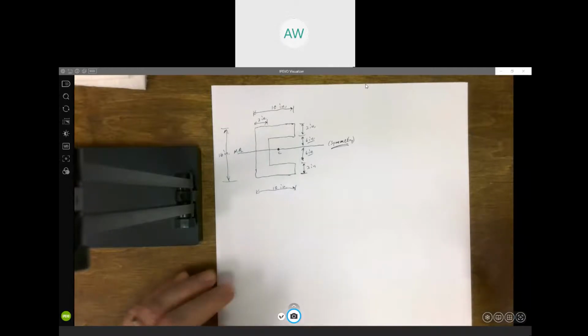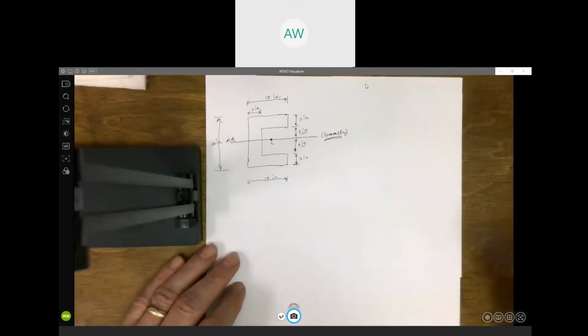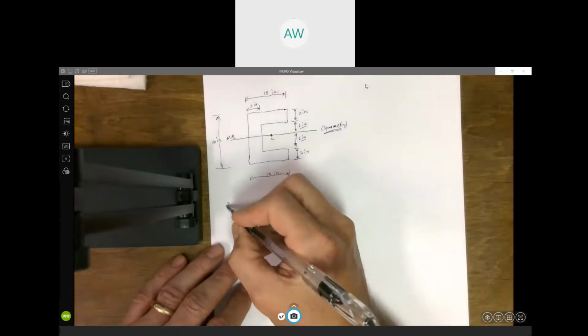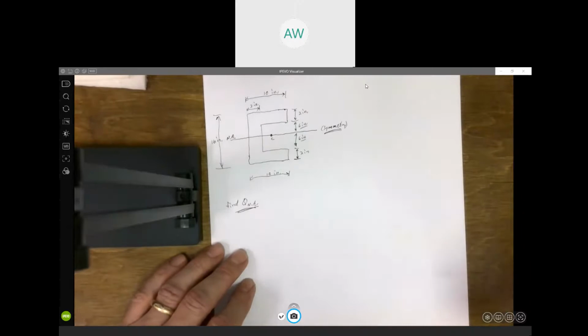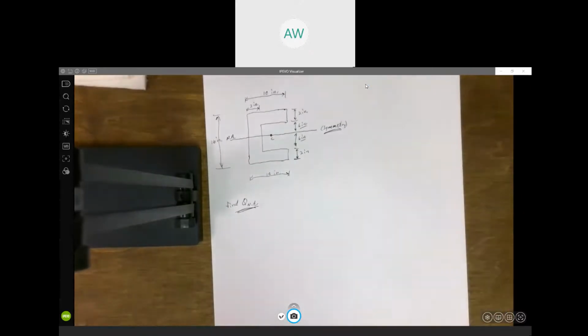So say we want to calculate Q at the neutral axis. All we're looking at is the area above. Now, I didn't mention this when we were defining the terms of Q. I said it was all the area above y prime. You could actually do all the area below y prime, and you would get the same number, but a negative. So sometimes if it's a lot less work to do the area below y prime, you can do that. Just remember you're going to get a negative number, so disregard the negative, and that would be equal to Q for all the area above y prime.